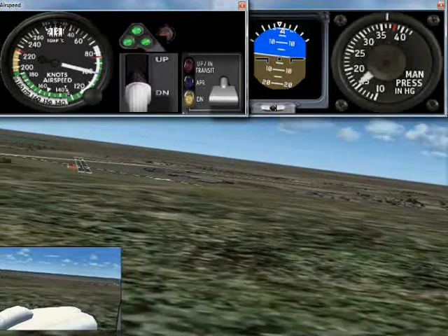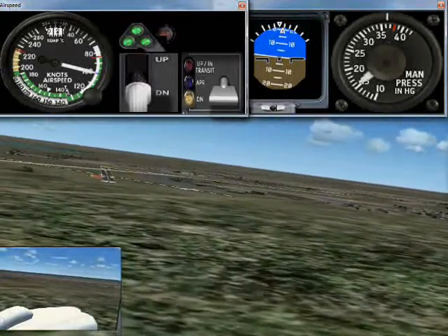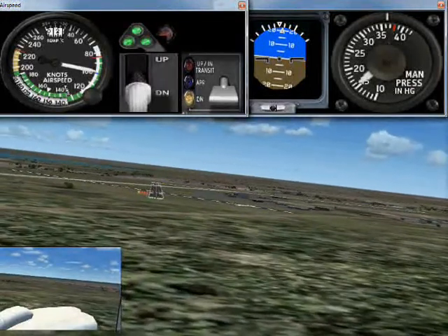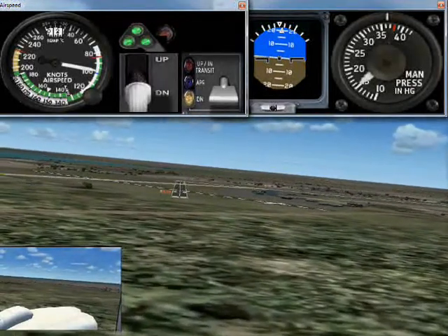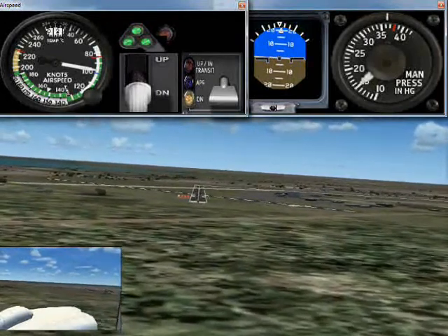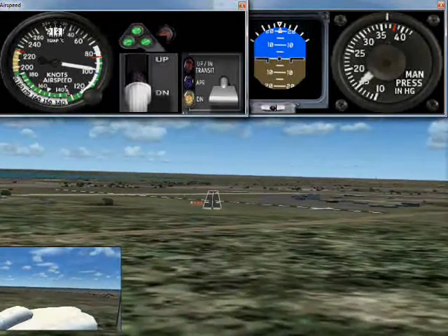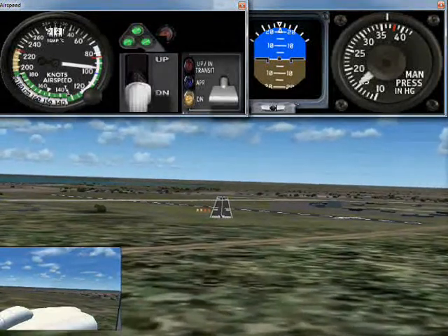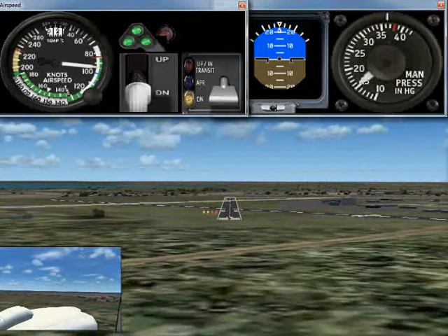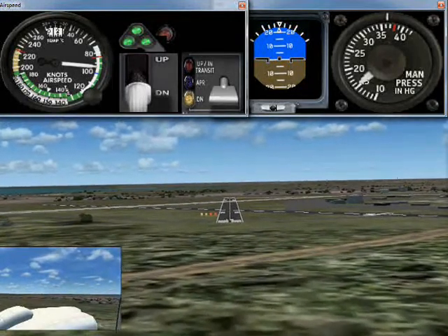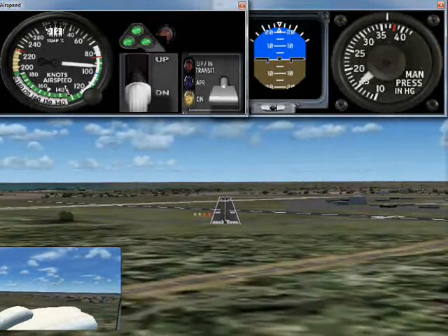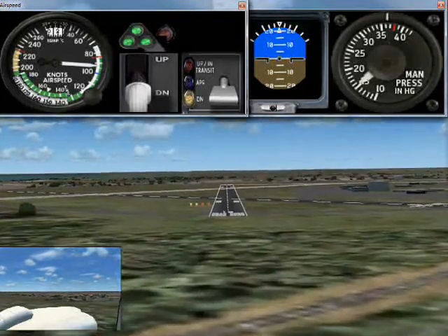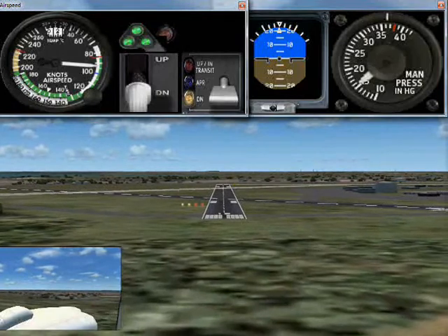Now, as we turn on to final approach, we begin to sense precise visual flight path information, and now have the ability to correct both flight path and airspeed precisely, which is a power variable situation. Therefore, for the remainder of the final approach, we will control flight path with pitch attitude and airspeed with power. We are now aiming for the threshold crossing height with pitch, while coordinating power adjustments to maintain the airspeed constant.